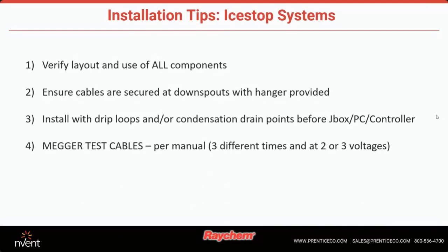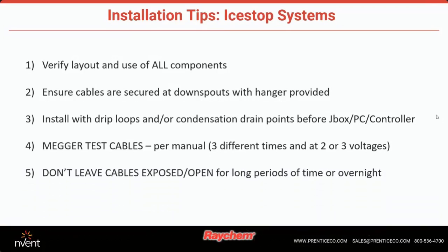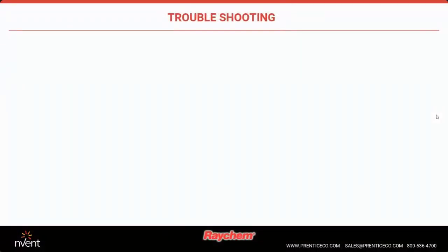Again, Megger testing the cable. I can't express this enough. This is very, very important, and make sure you follow the manual and guidelines to do that. And don't leave the cable exposed. Again, this is another very important tip, which is why I'm putting it on all these slides.